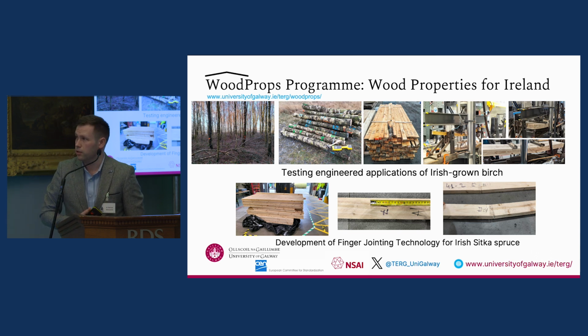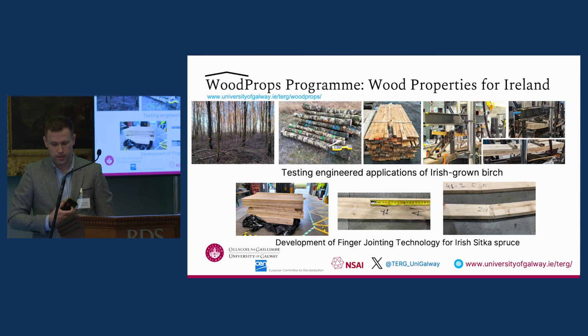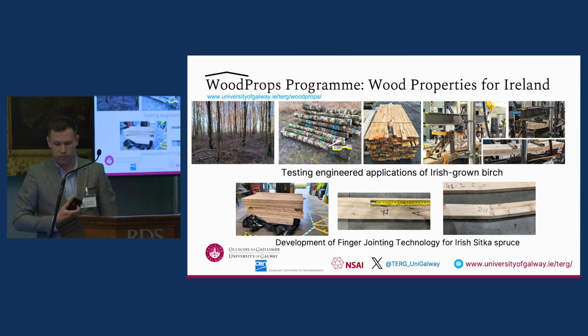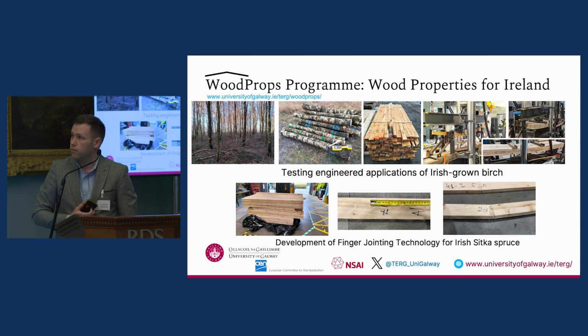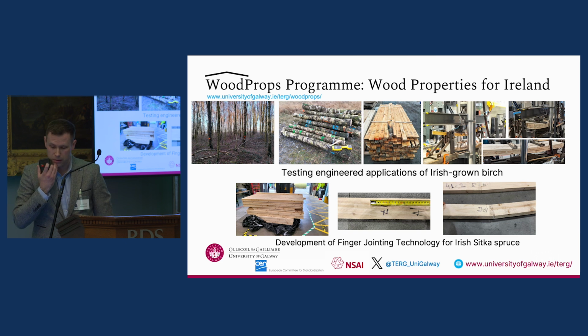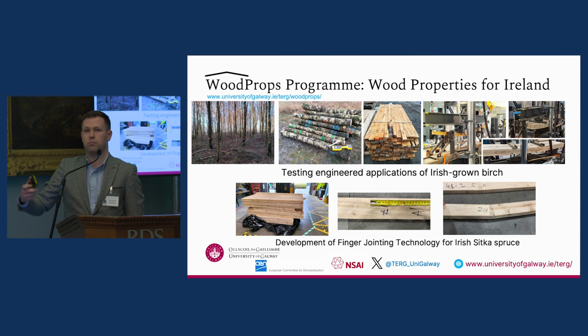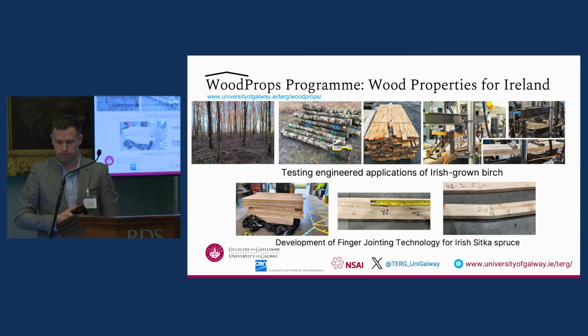Lastly, to highlight just some recent projects that we work on right from the forest through to construction products. Upper images show testing of engineered applications of Irish-grown birch through flooring panels or used in dowels, and also development of finger jointing technology for spruce, but that would apply to any species, where you can make much bigger products from smaller elements when you use finger jointing.